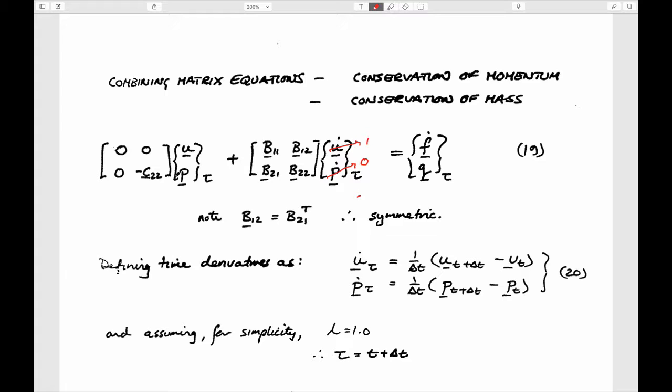Let's have the pressures kept to be 0 here as well. And if that's the case, so we apply some deformation here, then it means this vector times this gives us some magnitudes of flow rates. And so what it's physically saying is that as you're compressing it, you're squeezing fluid out of it, and the rate at which you squeeze fluid out of it is given in terms of this continuity equation on the bottom, which says something about the rate at which material is removed.